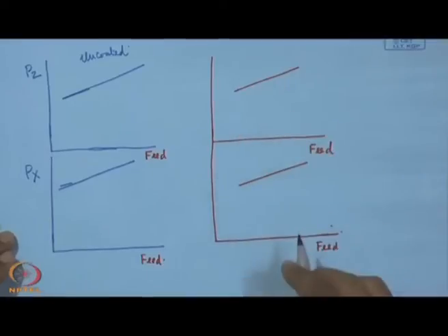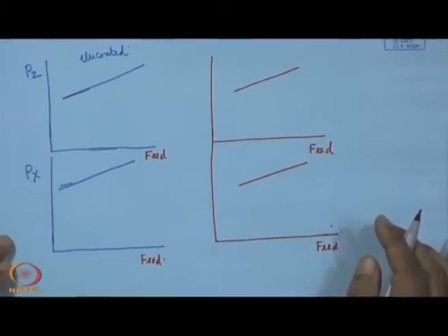This is very important to compare, because in the low speed range it is mostly the sticking tendency and built up edge formation that are more critical than the wear on the tool, because in the low speed range wear does not take place at such a rate or with such a mechanism that leads to rapid growth of wear.